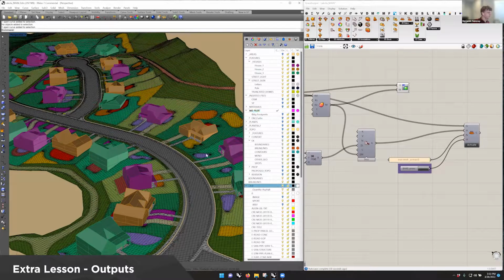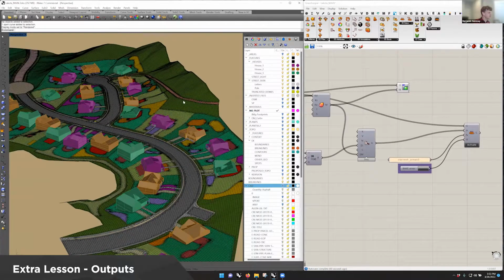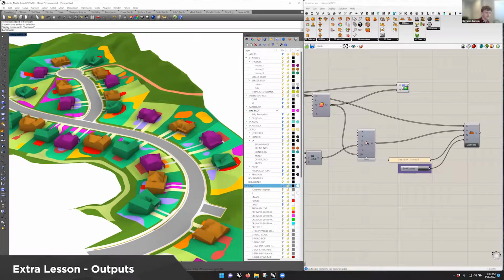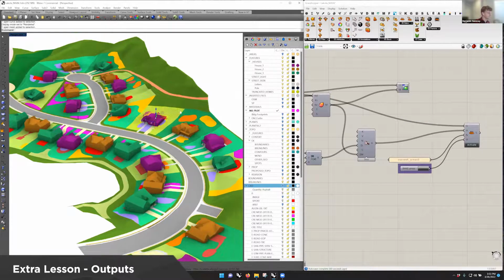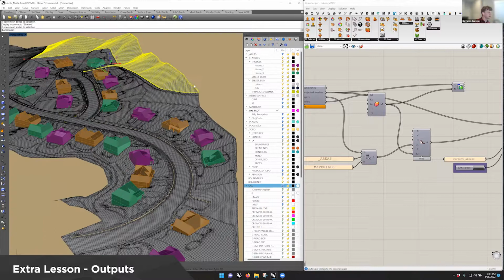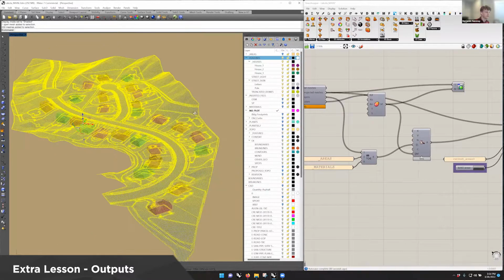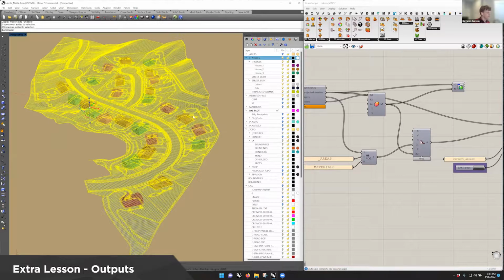Turn it off. And you'll see that's coming into Rhino. And if I go into a rendered view, you'll see that they're all the same color. Well, I still have this previewed. Or they actually all have the colors. I think I kept the materials on there somehow. But typically it doesn't categorize them well. It doesn't put them on specific layers. You'll see that they're all on that layer that I have them on, features. So they're not all on their own individual layers or anything like that.